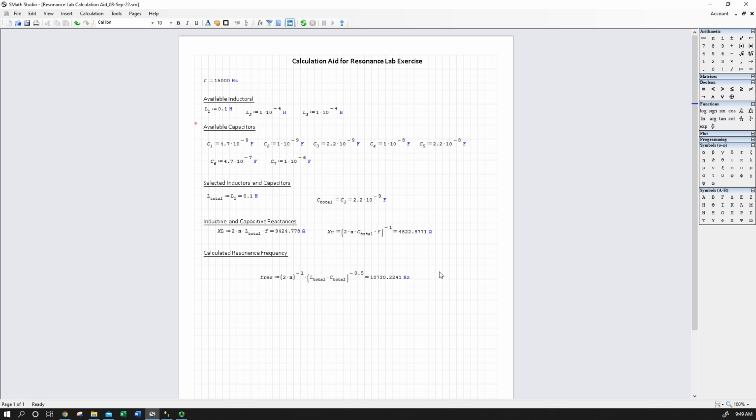So I'm going to take a pause in the recording, and then I'm going to switch over to my Picoscope. I will have a built circuit with these values of components, and we'll start exploring some measurements that correspond to these calculations of resonant frequency, and also take a look at how the Q value of this circuit, so the reactance values of my non-dissipative components, my inductor and my capacitor, compare to the total resistance in my circuit, and what that looks like in terms of the bandwidth of my resonant circuit, or the frequency spread over which I'm dissipating how much power.